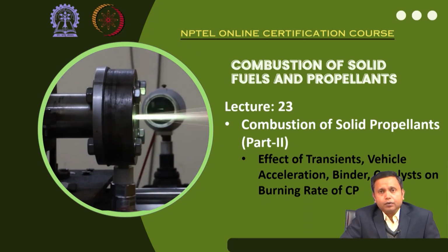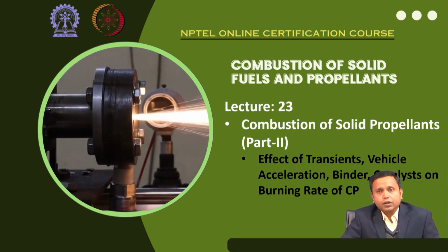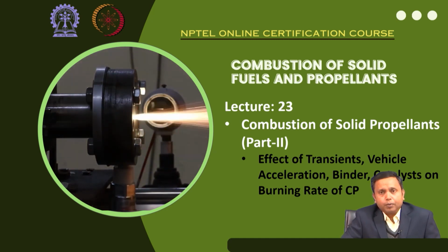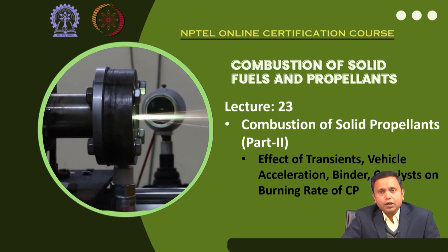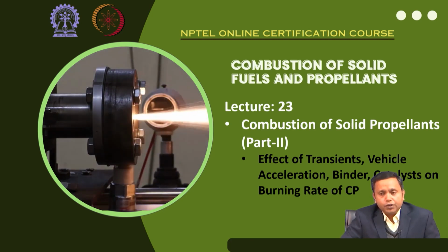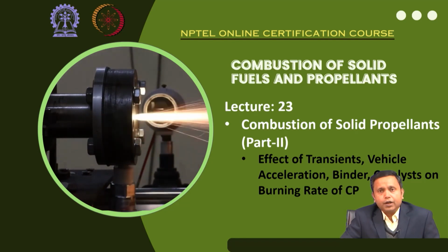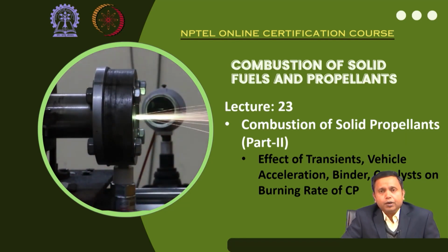Once the flame heats up the propellant surface, the heat is going to transfer through conduction, and the initial temperature of the propellant is going to change. We have seen that Ti is going to change to the surface temperature Ts. Now, what about the influencing factor of this variation of Ti? We discussed that through a temperature sensitivity coefficient, and we have also said that for double base propellant the temperature sensitivity coefficient is comparatively higher than that of composite propellant.